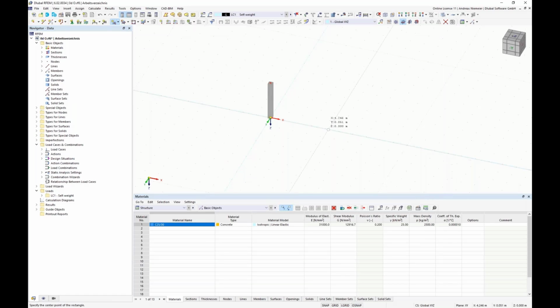Now we can place this foundation plate in space, and of course we know the center is in the middle of the column, on the leg of the column. The graphical appearance of this command is pretty good to explain, because we can make a square-shaped foundation, a rectangular-shaped foundation with an orientation in X, the same in Y direction, or a big square, whatever.